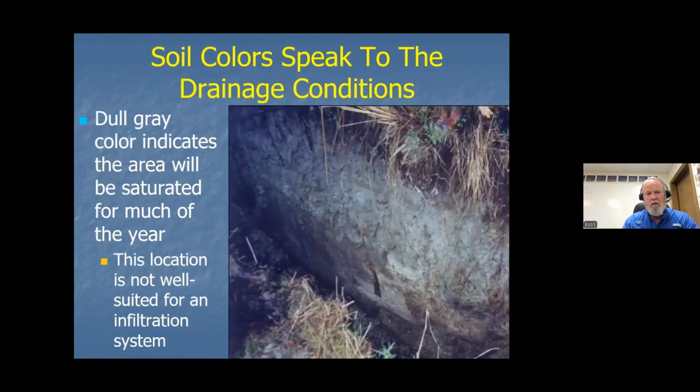So you're looking at soils that are gray. It may be that you would run into a soil that was naturally gray, ash, for instance, but often in a soil that has been wet, dried out, wet, dried out, the iron will be removed from the soil. And so you will sometimes have a soil that indicates that it's often wet.